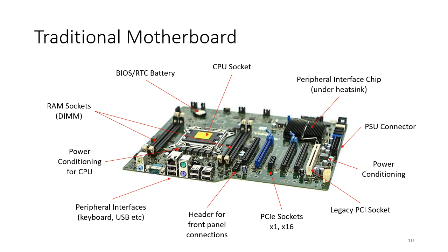Now, moving up again, there's a battery there. You typically see a battery which is used for maintaining the BIOS contents. A modern BIOS might use flash, but older BIOS use a battery-backed RAM, and that would power the real-time clock. So there's a battery there, typically like a coin cell battery, that you need to replace every 5 to 10 years, depending on the unit.